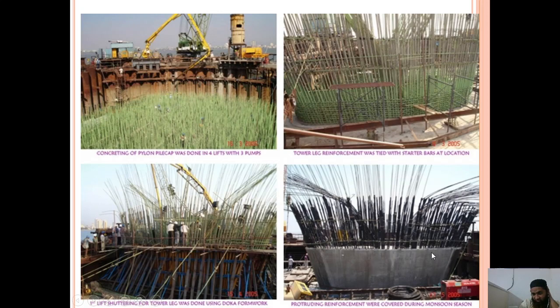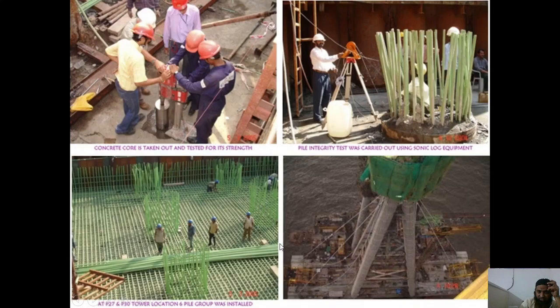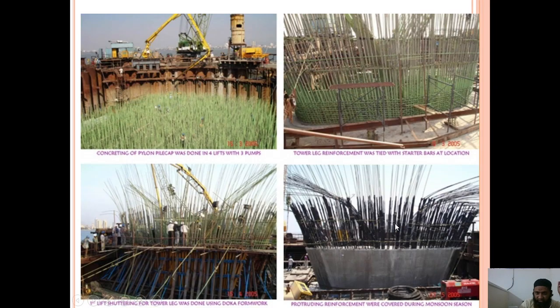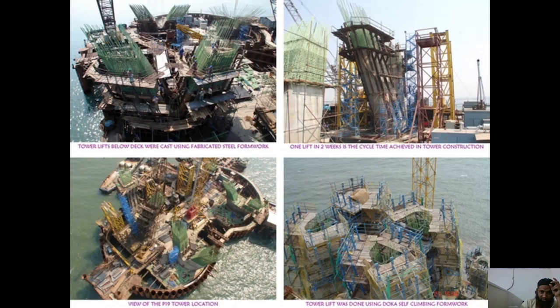You can see here this part is constructed in stages, as I have told you. First lift shuttering for lower leg was done using formwork. Then the protruding reinforcement was covered. You can see all these. Let us see this construction first. The reinforcement was covered during monsoon season, because it couldn't be completed in a short span. So even that care had to be taken. You can see this type.